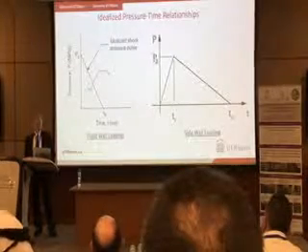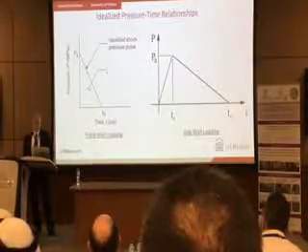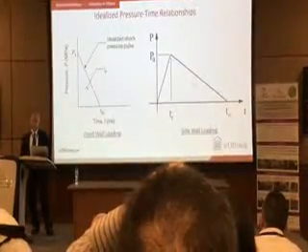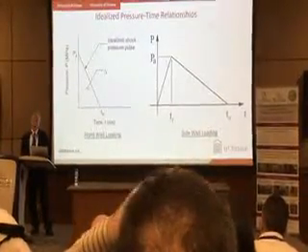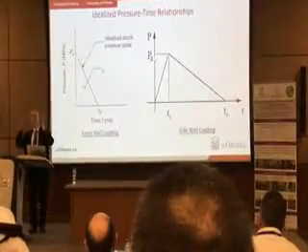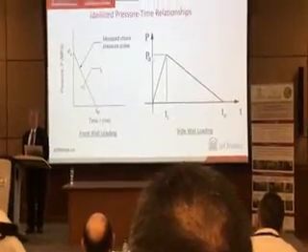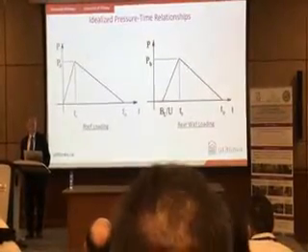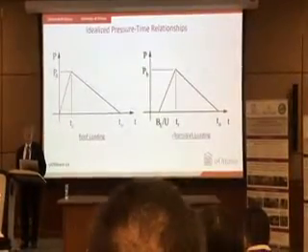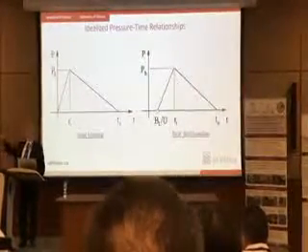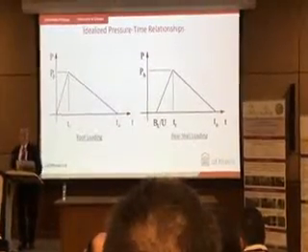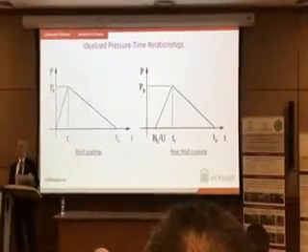So the one on the left-hand side is for front loading. The one on the right-hand side is side loading. But notice that in side loading, we don't use reflected pressure because nothing is reflecting. It's parallel to the blast pressure. And similarly, roof loading has this kind of a shape. And rear wall loading, there's some delay by the time shock wave travels and goes to the back of the building. There's some time delay, but other than that, these are the blast parameters.